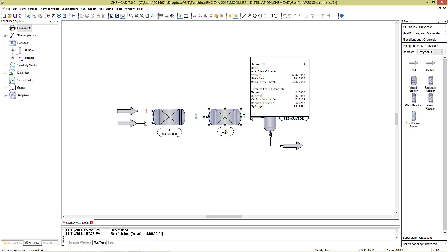It's going to be a kinetic reactor, which means that it will have a specific conversion type to it. In industry, I know it is usually around 20-25% per reactor, the conversion that you get for methanol synthesis. So you will still have a lot of gases that you have to recycle. So you just have to tune it to be very close to 2.